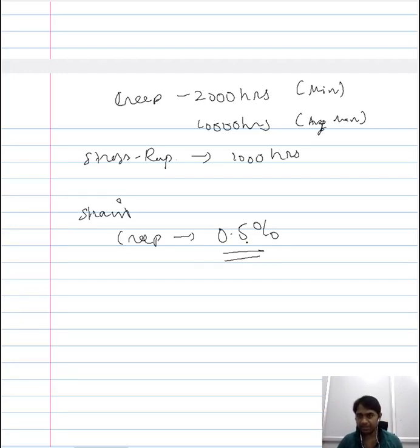This is primarily because we stop the creep test once the tertiary stage sets in, once you observe a significant change in the dimension, or a significantly increased rate of change in dimension. You stop the test, and for good reasons, because we want to consider the life of the material and the strain of the material.